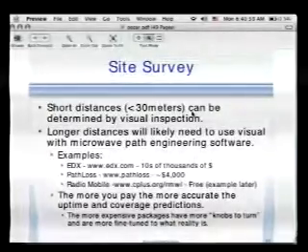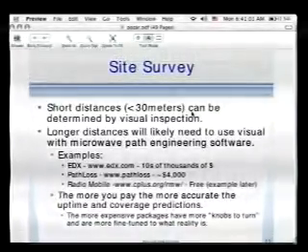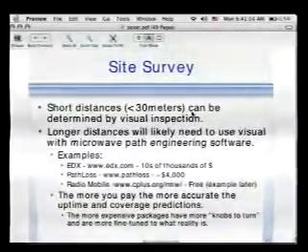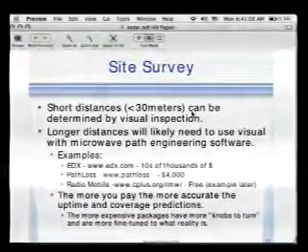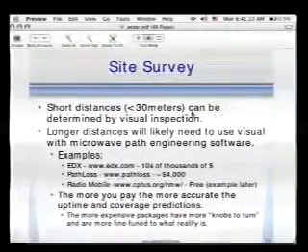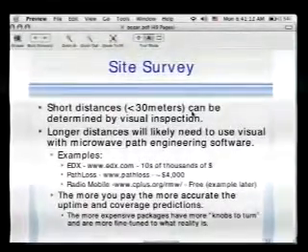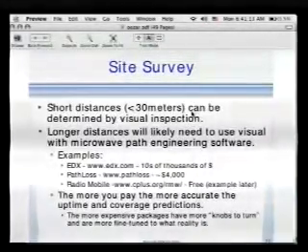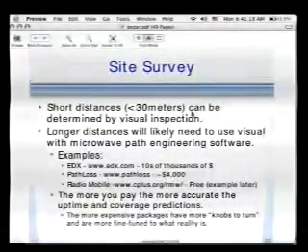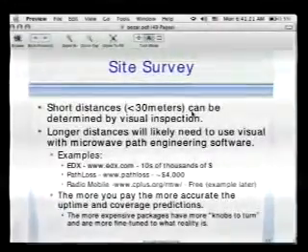If you want something really cheap, it's actually free. There's a package out there called Radio Mobile, which in some ways is more accurate than the others because it uses the Shuttle RF elevation modeling that they did about 3 or 4 years ago. So it's actually accurate to about 1 meter for elevation and terrain.